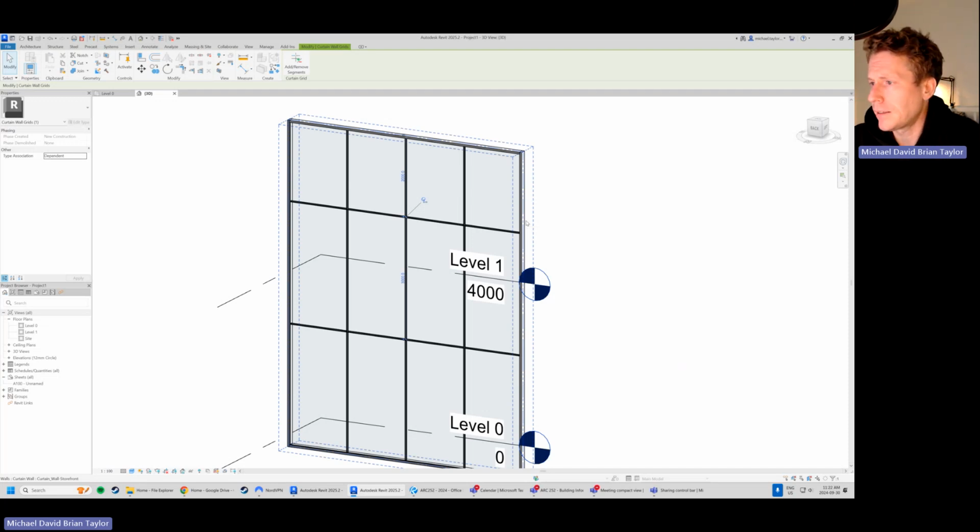But in fact, this little pin, which is vague and totally not helpful unless you know what it's doing. What we want to do is unpin this horizontal grid here. A couple ways you can do it. You can jump up here to the modify panel and hit our little unpin. So unpin is going to let us unpin this piece of grid.